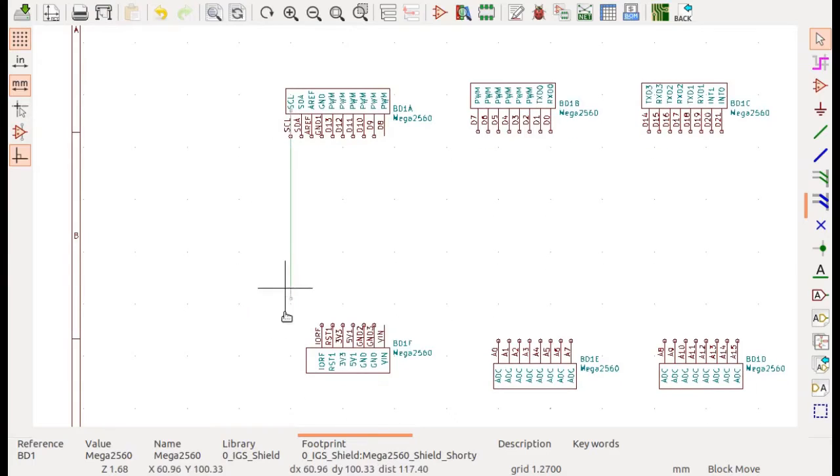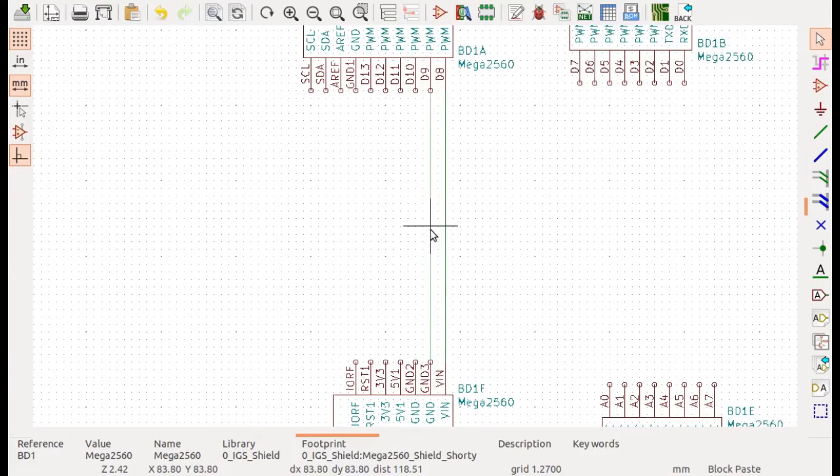You got this wire. Now we're going to do a Control C. Notice as soon as we did Control C, the wire popped right back to where it was. And we're going to do a Control V paste. And now we can move this copied wire over to the next position. Make sure that it's connected directly to both the top and the bottom pins, not overlapping. When you click, both the circles should go away. That shows you that that wire's been connected. We can go over two more, say paste.